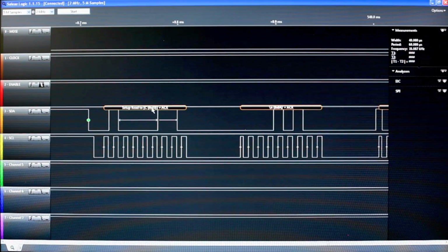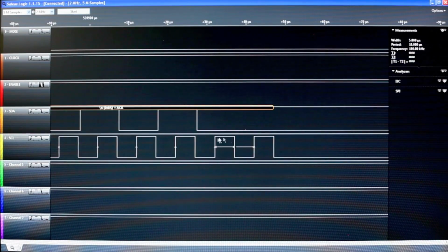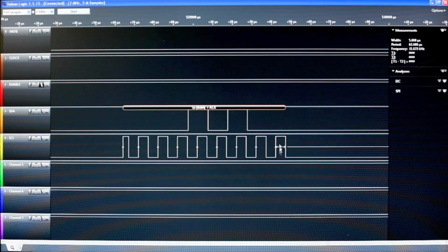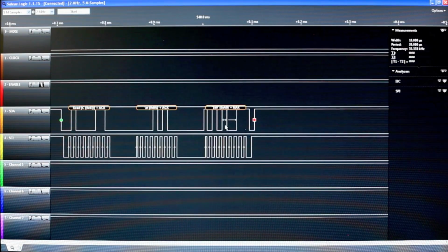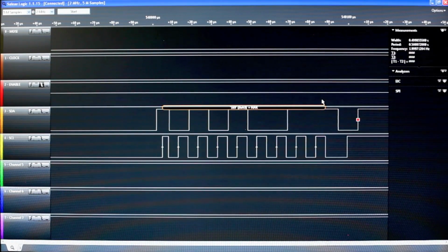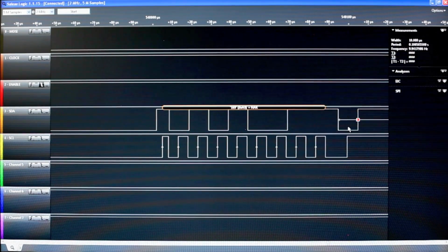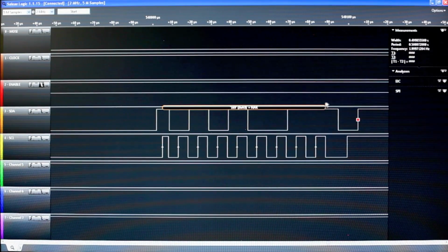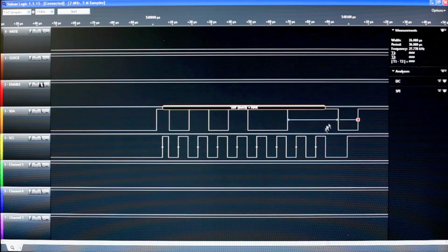So you'll get the command, which if you look in the data sheet says it's 43. And the analyzer has seen an acknowledge. There's the acknowledge right there, the very last 9th transition. That's a 0. And then there's the next byte here with acknowledge. Now check this out. The very last one, I wasn't sure what was going on at first. This is the last heading bit plus NAC, which is a negative acknowledge. This is how you come out of a read operation with the HMC6352. So not a big deal. This is doing what it's supposed to, and there's the end of the transmission.